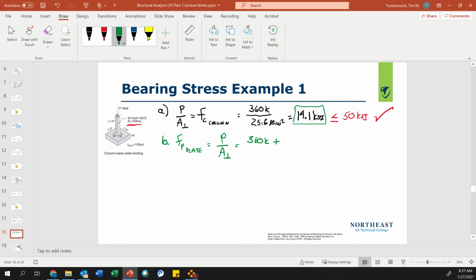Okay, so I'm on page 278, and we have density, unit weight density gamma, which I'm thinking they're saying pounds per foot cube, but it's pounds per cubic foot. I look at steel, and it weighs 490 pounds per cubic foot.